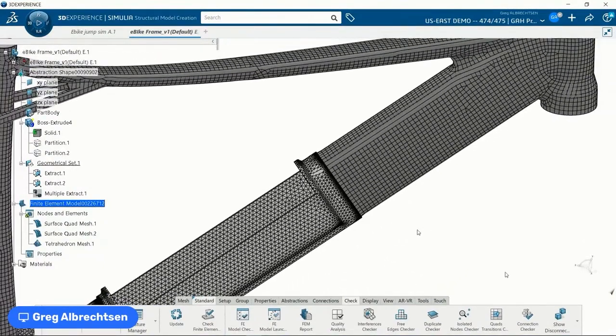And for this model, it's probably just fine the way I have it, because I have a circular tube structure mounted down to a solid structure. So just by the shape of the geometry itself, I don't have to worry about capturing those rotational degrees of freedom, because that's all going to be taken up in the actual shape of the geometry.